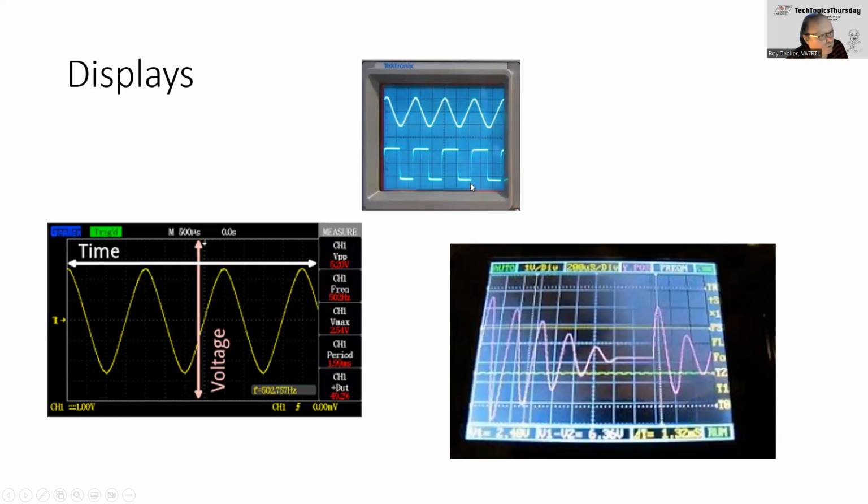Your typical analog scope that you can find at your swap meets will just give you a waveform, and by the height of the waveform, you can set this like at 10 volts per division, and then you have to count how many divisions there are to determine what your volts is. So, if it's 10 volts per division, and this is 2 divisions, that would be 20 volts. And you would do the same thing for frequency. You would see what your period would be across each one of these divisions. So you would count where one cycle would be and calculate it that way.